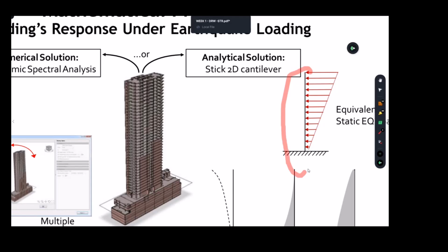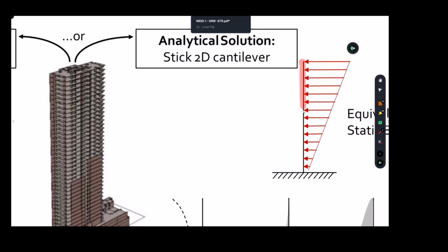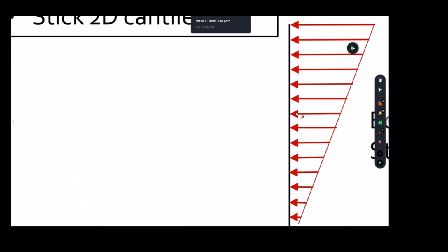And as I said, they use something like ETABS or Space Gass, but they have really detailed information. It's not just a stick, as you can see. If you go to Space Gass or ETABS and click on that line, they have defined things accurately. They have told it that this element has the correct engineering properties in terms of its inertia, the elastic modulus, the concrete properties, the dynamic properties.